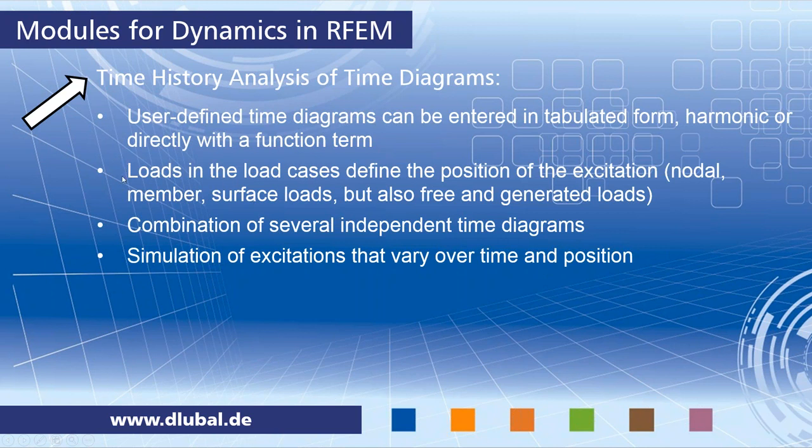You define loads in load cases in the main program RFEM. This is the point where you define the position of the excitation function. The big advantage of this is that you can use all loads that are available in RFEM. You can use nodal loads, member loads, surface loads, but you can also use free and generated loads, which are very flexible in form and size. This is all then combined with functions varying over time. So this makes the time history analysis very flexible.